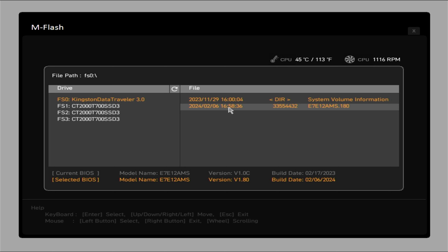And step down time is the same thing, but in reverse. So you can adjust how quickly your fan speeds ramp up and how quickly they ramp down. So if you want to extend that, it might mean that your system's a little bit noisier for a little bit longer, but you won't just suddenly have a massive drop off in the fans, and it will be a much more constant noise. So lots and lots of cool stuff here.